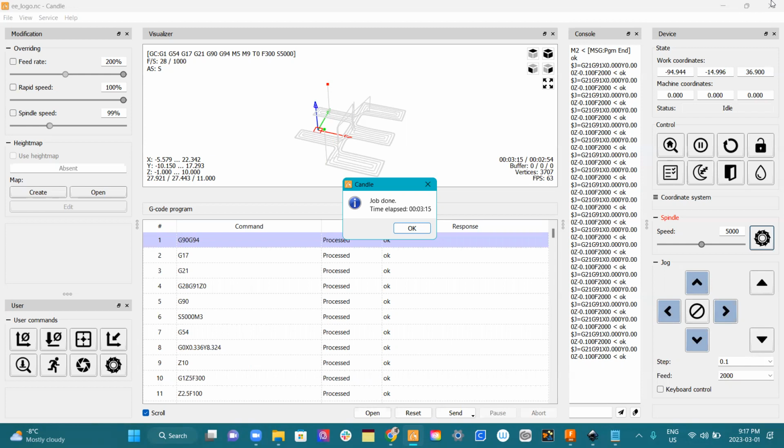These are engraving bits. They're like a triangular tip, and you wouldn't want that on that. You have to be careful when you pull these out, because this is a piece of wax, and I've stabbed them in my fingers too many times. This is an engraving bit, mainly for roughing up the material. It spins, but it doesn't do a lot. But it leaves a really nice finish. If you do a square with this, it'll look kind of frosted. That's why I used it on the plate there, for the frosting. It makes all this burr, so that's good for holding ink.